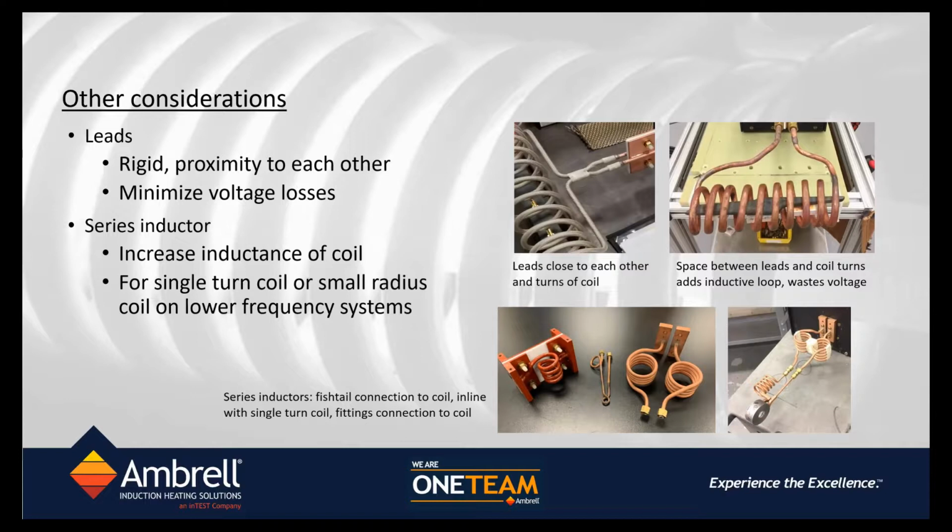So if the coil had only a single turn, or if it was a very tiny coil, you may have to incorporate some extra matching coils, as they're called, in the path of the copper tubes to aid the entire system to run at the frequency of choice. So there's a lot more to induction coil design than just winding the copper, as you see.